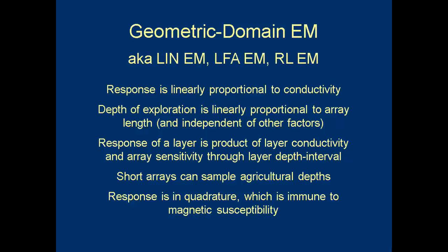The sensitivity of an array to a given range of depth in the sampling volume is defined by a simple function. The response of a layer that occupies a given depth range is the product of the conductivity of the layer and the value of the sensitivity function. Total response is the sum of the layer responses. These characteristics of geometric electromagnetic induction make interpretation of response simple and robust. Where responses of several arrays are available, estimates can be made of the conductivity, depth, and thickness of conductive layering.